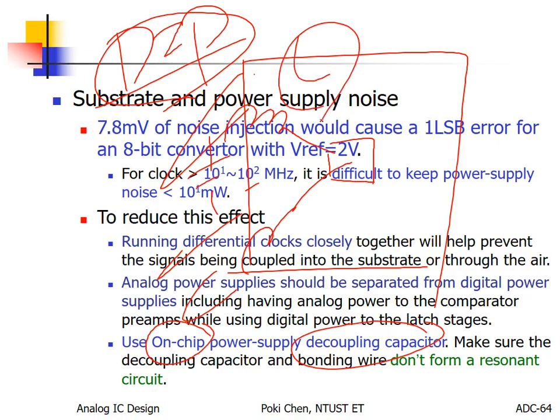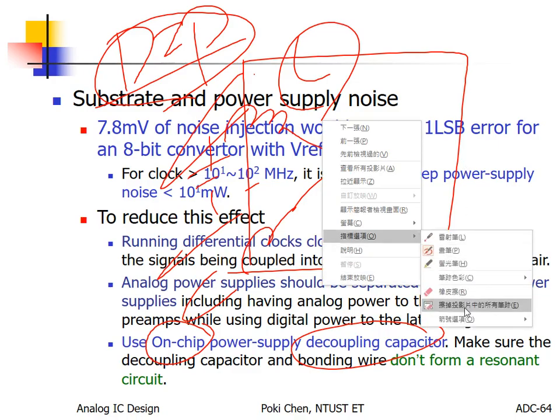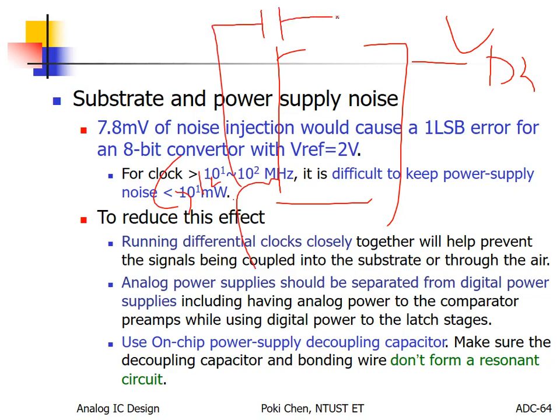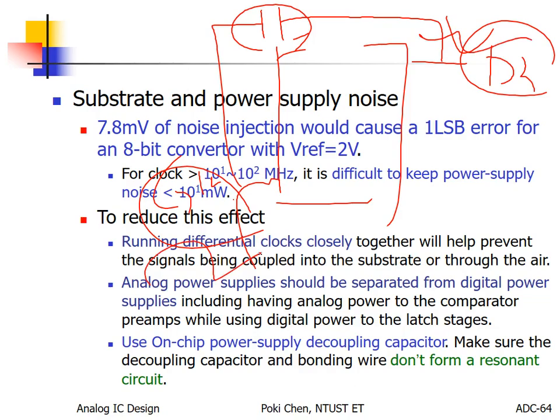So usually, if you are a good engineer for testing, between your VDD and your ground there will be some off-chip decoupling capacitor to stabilize the VDD and the ground, to absorb the noise on the VDD and the ground. That's it. But after that, how about your on-chip voltage? Again, I told you already how to connect your VDD or ground to your on-chip bare die.